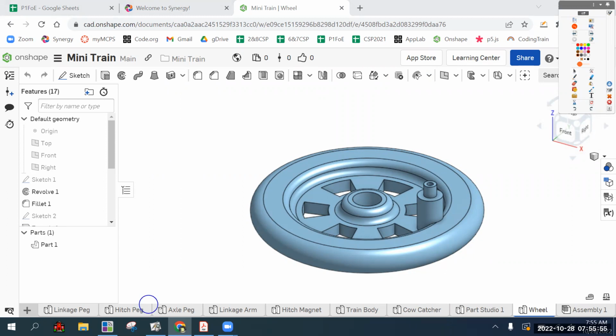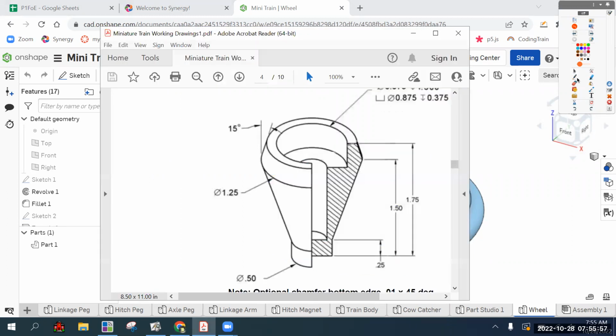Okay, so we aren't going to do the other way, since we can't do a tapered extrusion, which is super easy if that was a tool in Onshape. It is not. So we are just going to make the sketch, but ignoring the center part. Make a sketch that looks like this, just the right side, and revolve it, and then do the holes on the top, or the cuts from the top.